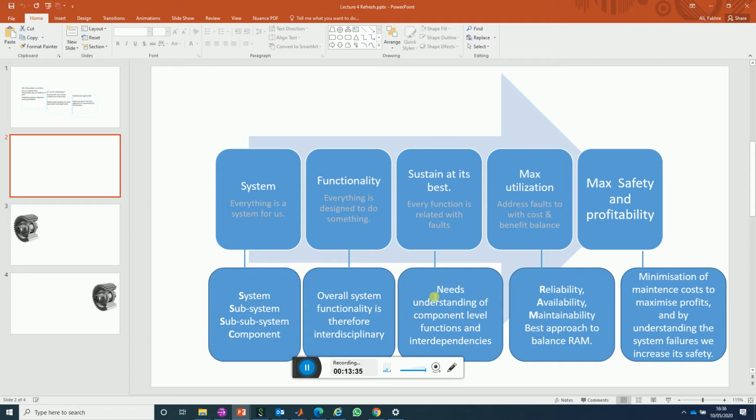We've studied in fluid mechanics that in order for the flow to remain laminar and steady, we need to have smooth inner surfaces in the pipe. So if, for example, over the time the particles start to accumulate on the inner surface of the pipe, it will start to build friction, and therefore the flow can be influenced within the pipe. It can lead to increase in pressure drop across the ducts. Right? So how can we better manage that, for example?